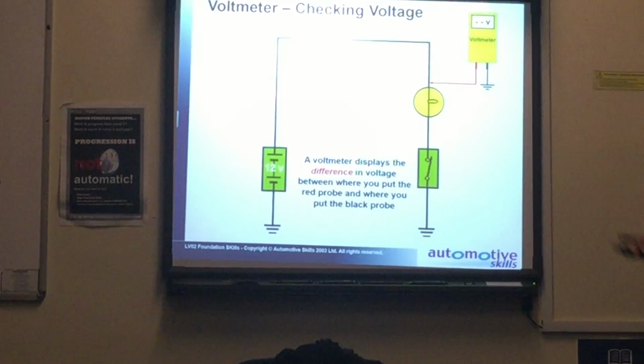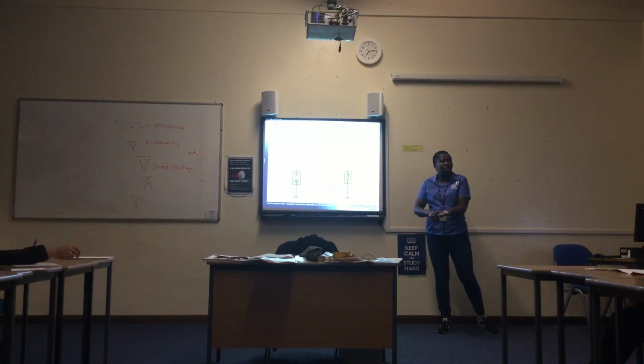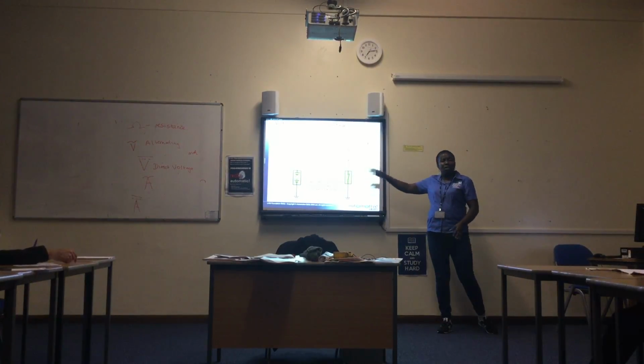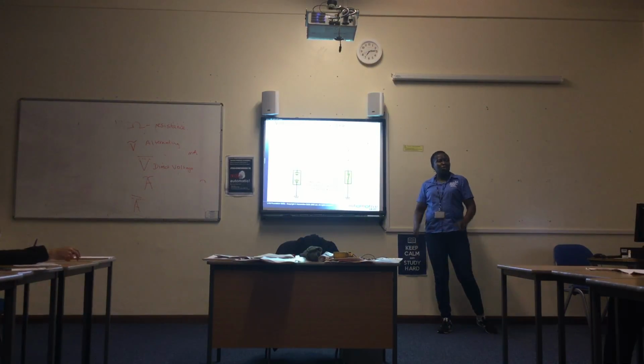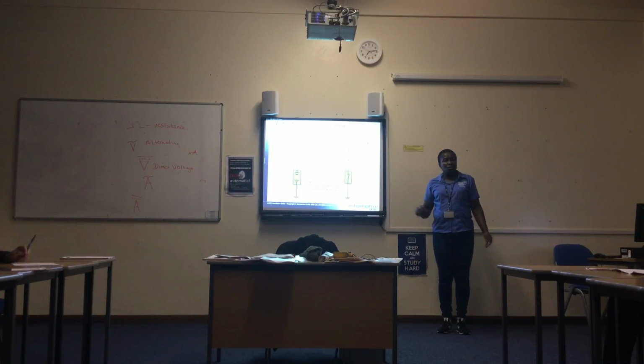Are we clear there? So if you have high resistance, maybe one of your contacts is not touching, or there's too much rust or dirt on the contact, so there's more resistance. Otherwise you should have very minimal resistance in all cases. So much so that at the end where you want the current, on the bulbs or the headlamps, you have enough current. If you light the headlamps and they are not bright enough, maybe there's a resistance somewhere. Maybe the wire is not touching properly or the ground is not earthed properly, so we trace the circuit to see where the problem is.